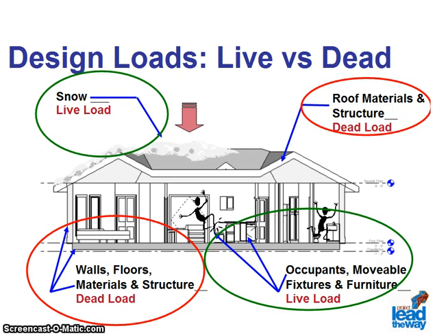Various loads act on the structure in conjunction with various other loads. Dead loads are fixed loads and are simply the weight of the materials that compose the structure. Live loads are the weight of anything which is not fixed in place. These could include snow loads, the weight of people and their possessions, and furniture in office spaces. Live loads may be variable during the structure's lifetime. In order to calculate live loads, the engineer must depend on building code specifications. These specifications are based on typical load capacity provided by structures that have withstood the test of time.